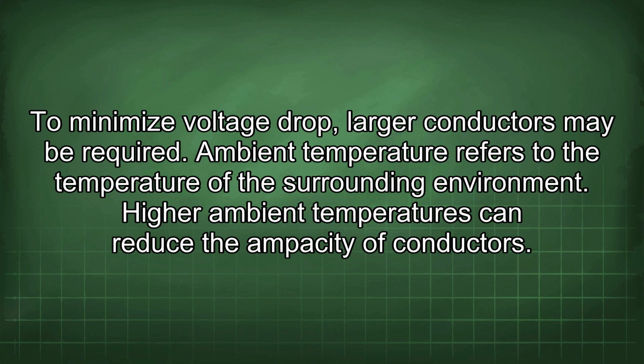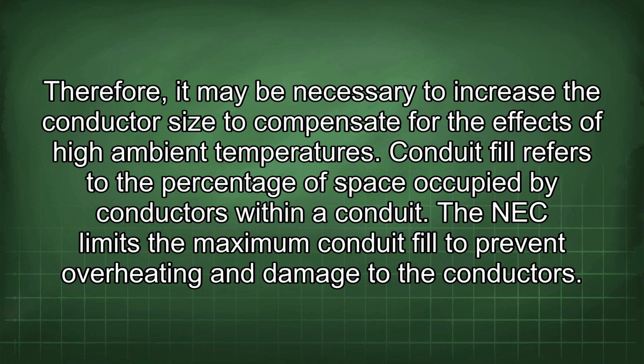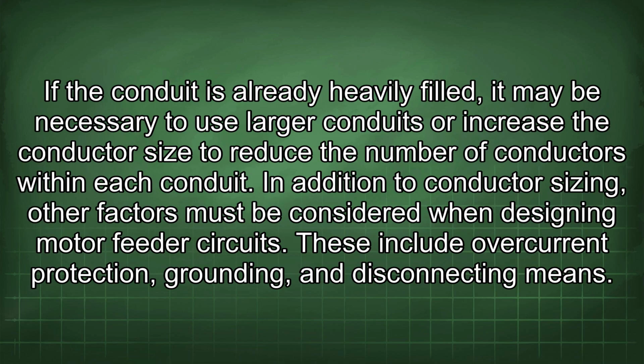Ambient temperature refers to the temperature of the surrounding environment. High ambient temperatures can reduce the ampacity of conductors. Therefore, it may be necessary to increase the conductor size to compensate for the effects of high ambient temperatures. Conduit fill refers to the percentage of space occupied by conductors within a conduit. The NEC limits the maximum conduit fill to prevent overheating and damage to the conductors. If the conduit is already heavily filled, it may be necessary to use larger conduits or increase the conductor size to reduce the number of conductors within each conduit.